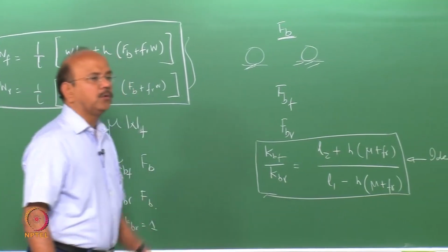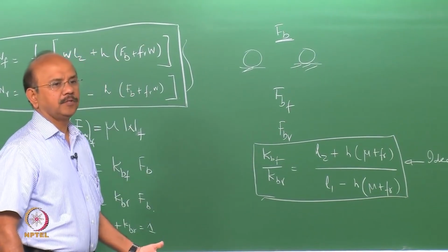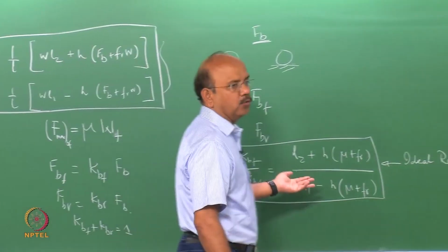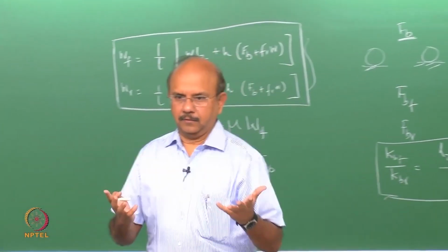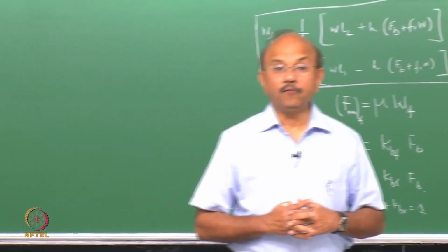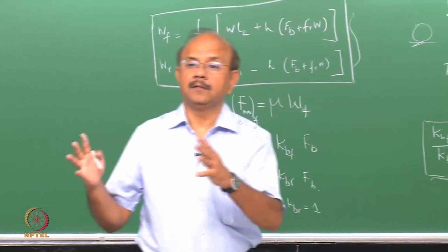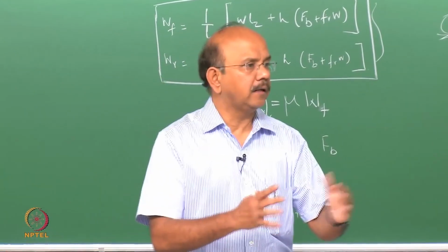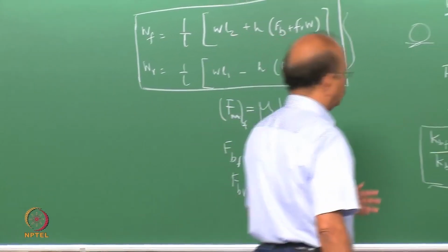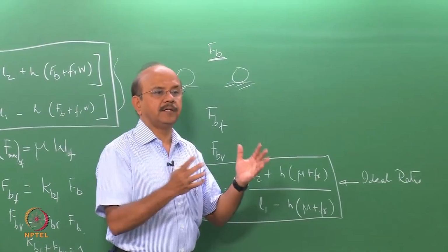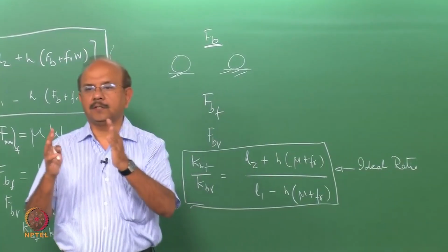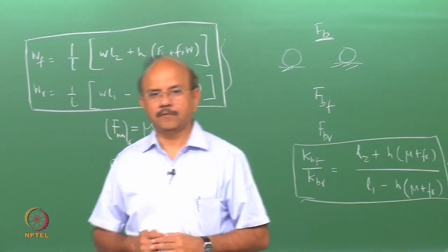Because when you load the vehicle, it is not necessary that L1 and L2, which are the distances from the CG locations, are the same. It may vary. For a truck, it would vary a lot more than a car, obviously. So, when you load, say for example a truck, then definitely the CG location can shift to the rear.